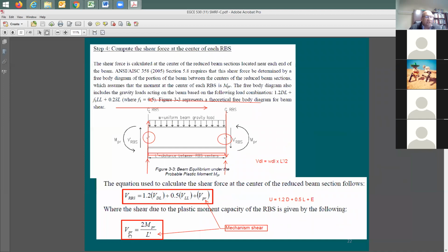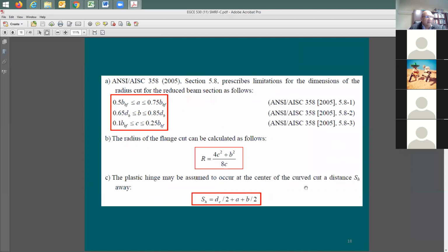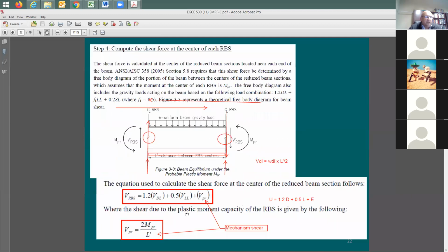This shear is just based on the member size that I have picked and chosen. So I have chosen here, let's say, W27 by 84 for the beam size. Based on this given beam size and based on the column-to-column span, based on my choice or selection when it comes to A, B, and C, now you start to push the moment frame all the way to the right with any given forces, and you keep adding force and adding force, you just increase the force.